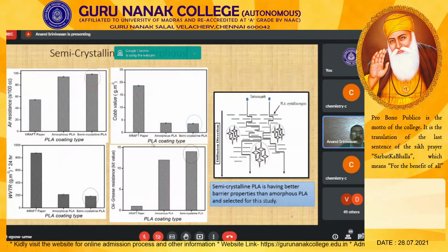And we made a product accordingly. We made a coating and coated abrasive. As you can see, the coating thickness is very small, and we can see a tortuous path is obtained with the semi-crystalline PLA. As a result, besides PLA having the methyl group, which is hydrophobic, this tortuous path, which is because of the semi-crystalline nature, also adds to the hydrophobic behavior of your coated abrasive product.